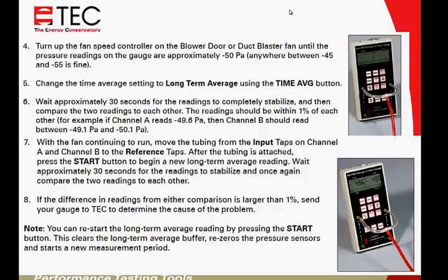But one of the other things that it does for people, it hits home that what they're really measuring on channel B is a pressure signal. And that's a key concept that we have with people calling in. I'll have guys calling and saying, yeah, somebody wants me to record what my fan pressure is, and they're just not in tune with what the gauge is actually measuring.